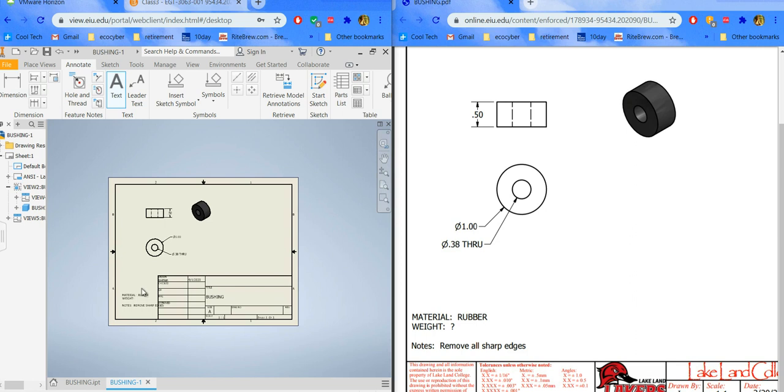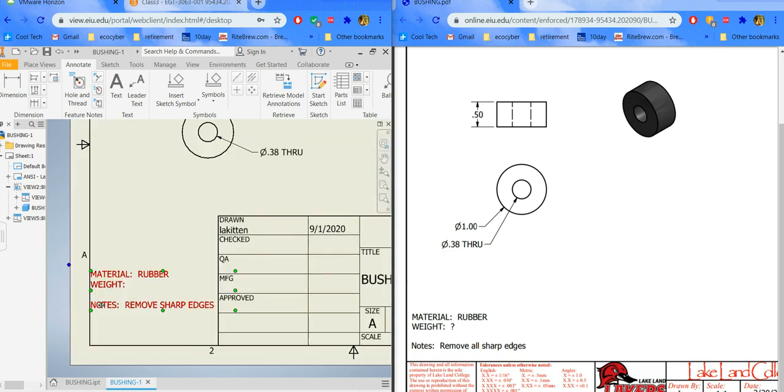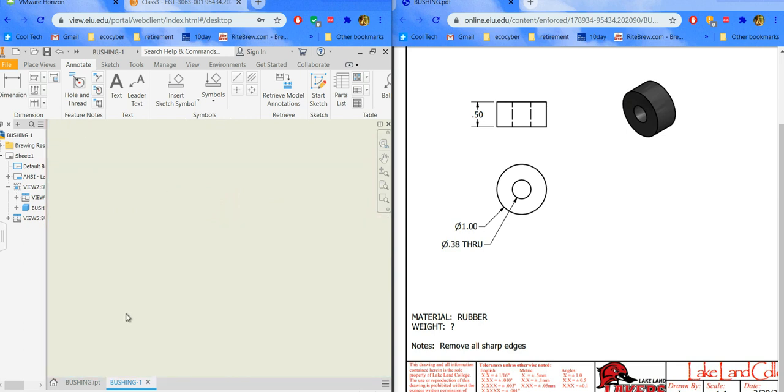I don't like my items here coming in, so I'll window these, and then turn it. Move them over a little bit. There they fit. You could also move them up high if you need to. Those are grips, so you can move those grips around and drag them around. If you get the arrows like this, you can move it around. But it fits, so I'll leave it there. If it doesn't fit, of course, it's very close. All right, that one is done.